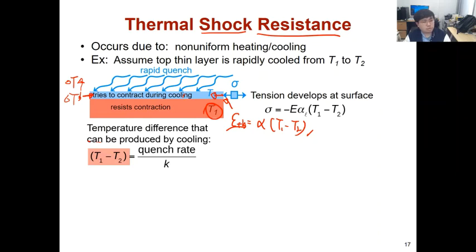However, due to the rapid change of temperature, the surface part will experience very high shocking or large stresses. Due to the large stress generation, this solid part will be broken. Some cracks will be initiated or propagated. So in this way, we should control the quenching rate. Quenching means the temperature cooling rate.